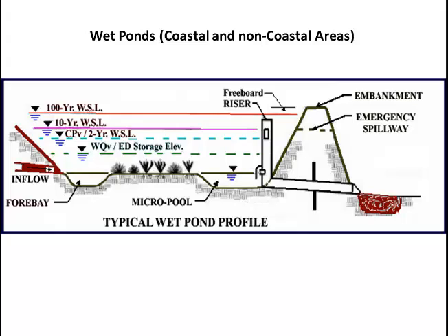The maximum extended detention and channel protection detention levels can be up to 5 feet above the wet pond permanent pool. The total area draining to the wet ponds is generally between 10 and 25 acres in order to maintain constant water elevations, though less areas are acceptable based on site considerations. Ponds should always be designed with a length-to-width ratio of at least 1.5 to 1. While developing the footprint of the wet ponds, the civil and landscape designers shall ensure compliance of all internal design features as specified in the DCR manuals.